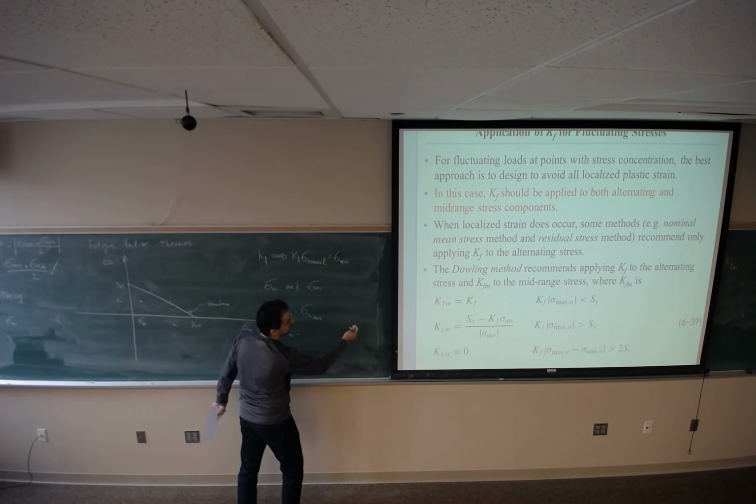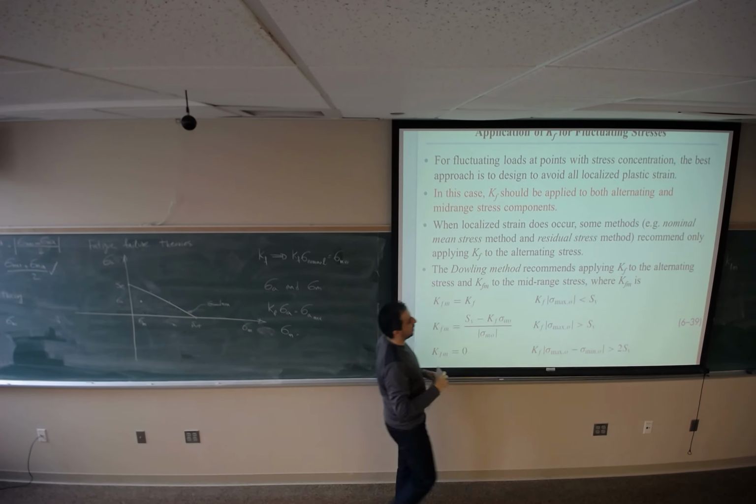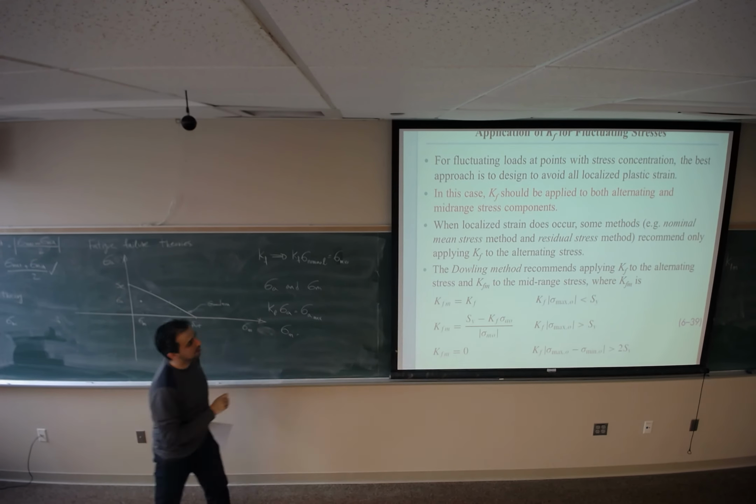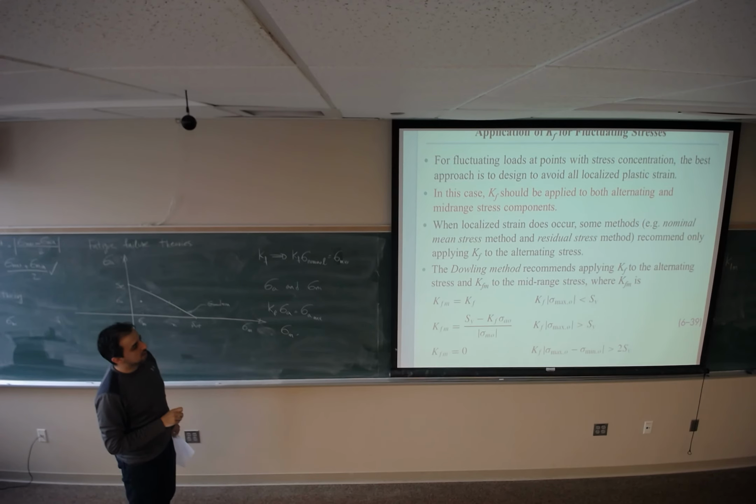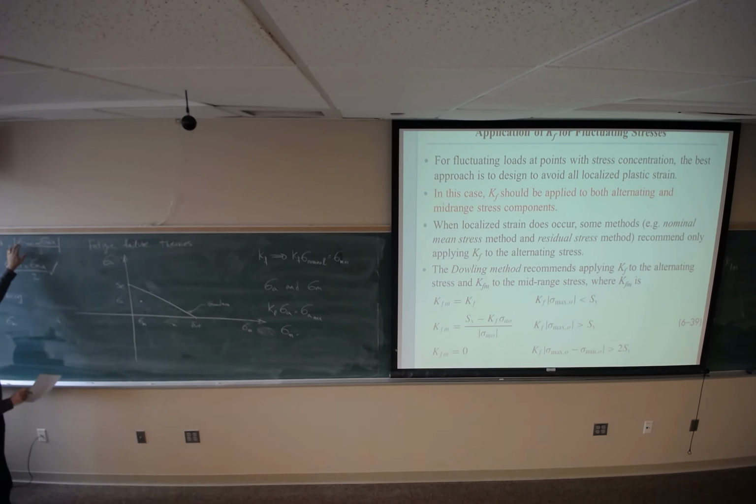You will find sigma max from here. You multiply by Kf, absolute value, if this is less than Sy.